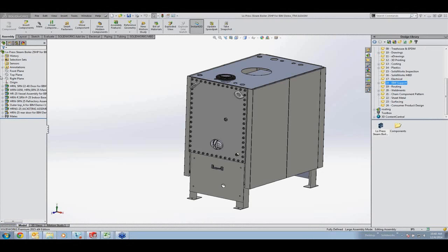I have some more further options here. I can choose to keep some features, etc. I'm just going to go ahead and get into the next window here. What this is going to do is remove the internal details, so you only see external faces. And also give us a preview. I should have a preview here in this right window.